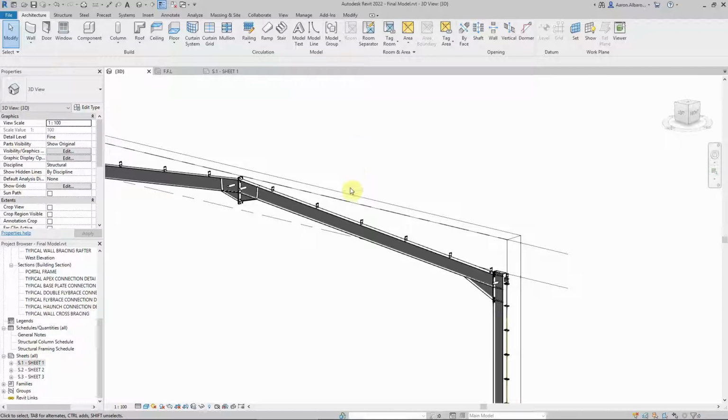In these cases, regardless, the load will be applied in this direction here, downward or upward. So we need this member mainly to be strong to resist this movement, not to bend either downward or upward. Therefore, we need them to be deep and not too wide.